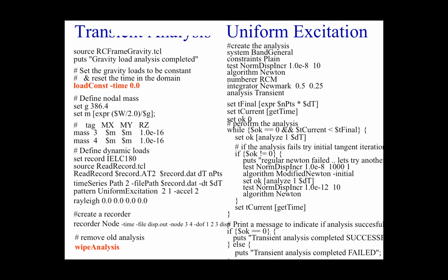I'm going to set those gravity loads to be constant. You don't have to put those gravity loads inside a constant load pattern. You can have them varying up as much as you want up to a certain point. And then when you issue the loadConst command, that will cause every load pattern from that point on to remain at that. Basically, the load factor doesn't change at any point after that. So every load pattern that exists before that command basically freezes. They don't change the load factors.